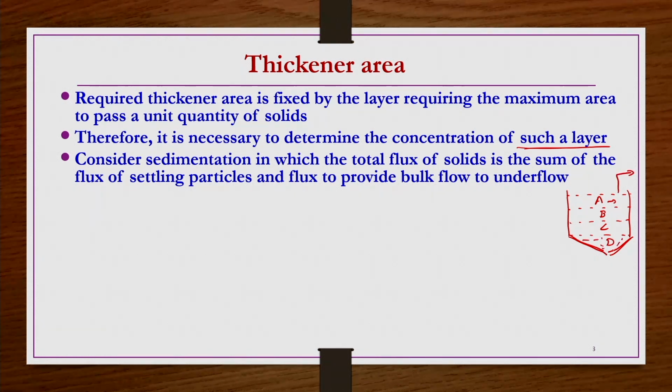D zone is a concentrated sludge zone from where you collect the solids discharge, and the feed is coming in somewhere in the middle of this sedimentation tank. Once the steady state is established, the feed rate coming in is equal to the overflow rate going out plus the solids going out. So, the layers that have developed, the different ABCD zones, are not disturbed. That condition we know as the steady state condition.